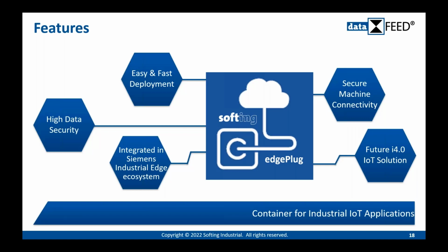That means you will be able to see all the variables internally in the structure of the Industrial Edge ecosystem, to be used by other apps, or, like I mentioned, via MQTT or OPC UA in external applications, to read all the information from the device and take it to third-party applications at the different levels that are required.